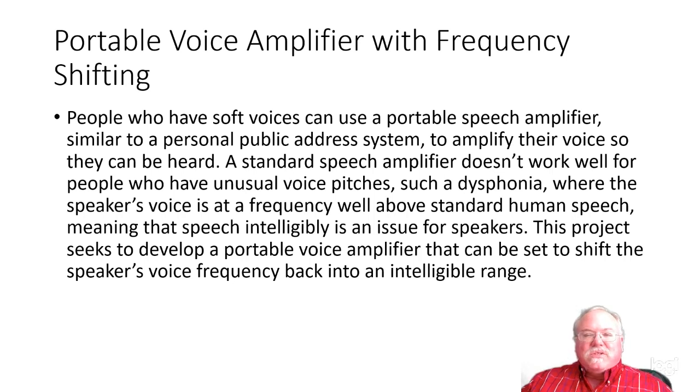That's due to what's called frequency clipping. The phone is actually clipping the high and the low frequencies from their voice to reduce the bandwidth. And when that happens, especially for someone whose voice is really high or really low, it's clipping out most of that signal so that you can't understand what they're saying.